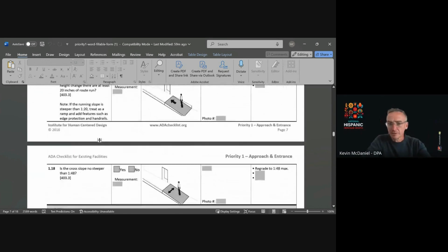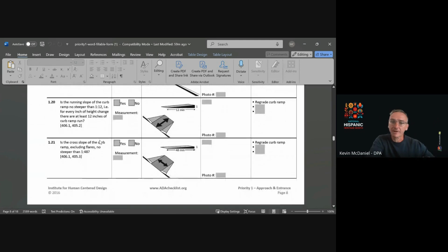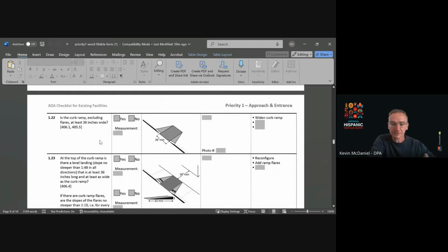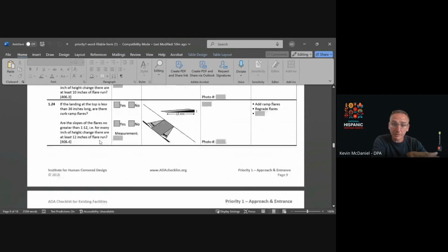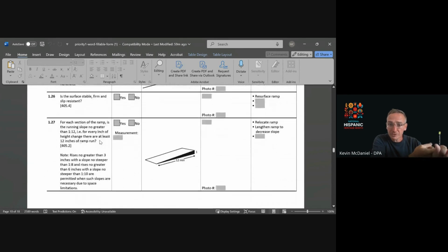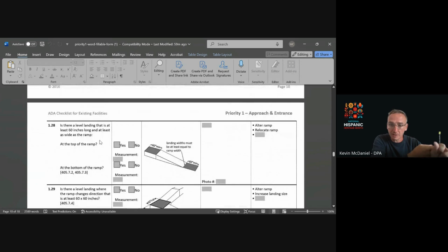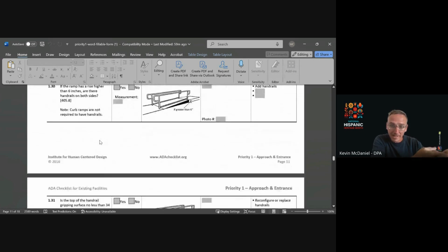Chris, if I could just real quick, because we have some ADA coordinators on the call who are going to be advocating with leadership for a need for facility inspectors and for funding. Just as a super high level quick check that they can do in their parking lots: do you have the appropriate 4% of your spaces? Are they disability parking spaces? So one of every 25 of your spaces. Do they have an access route?